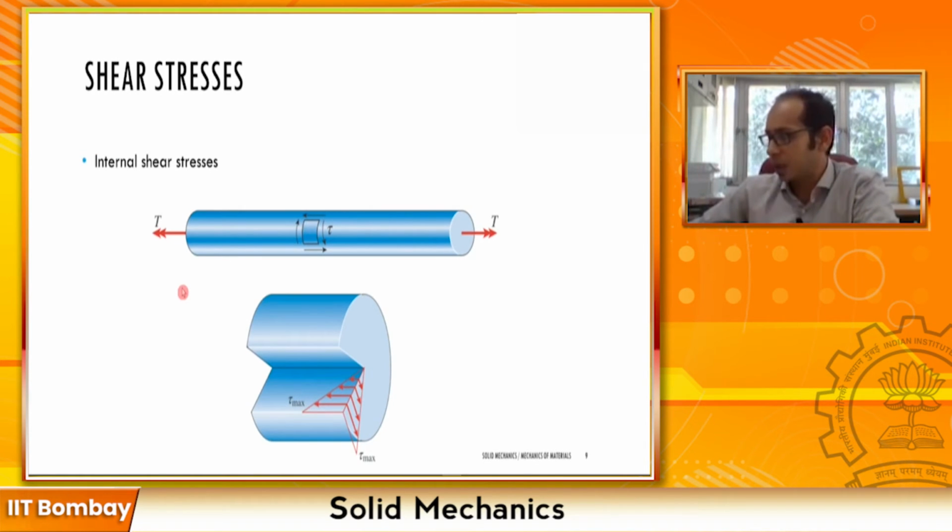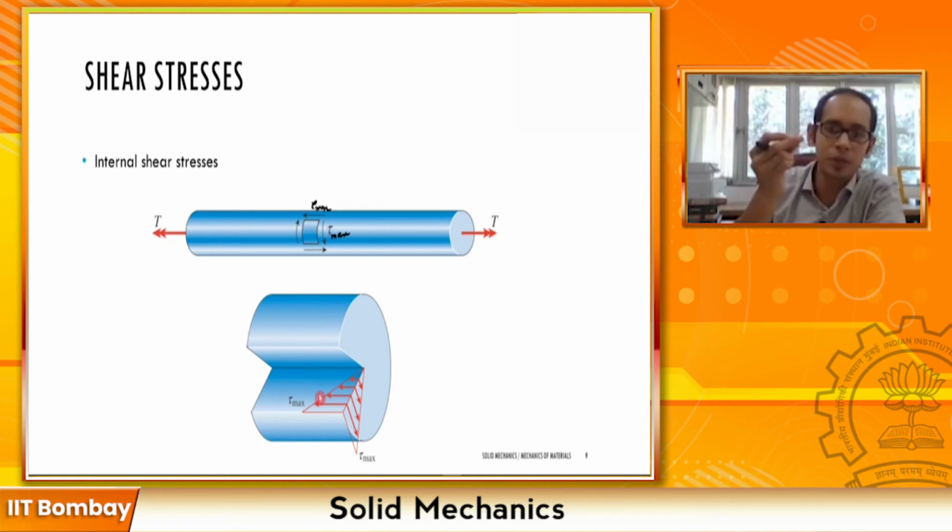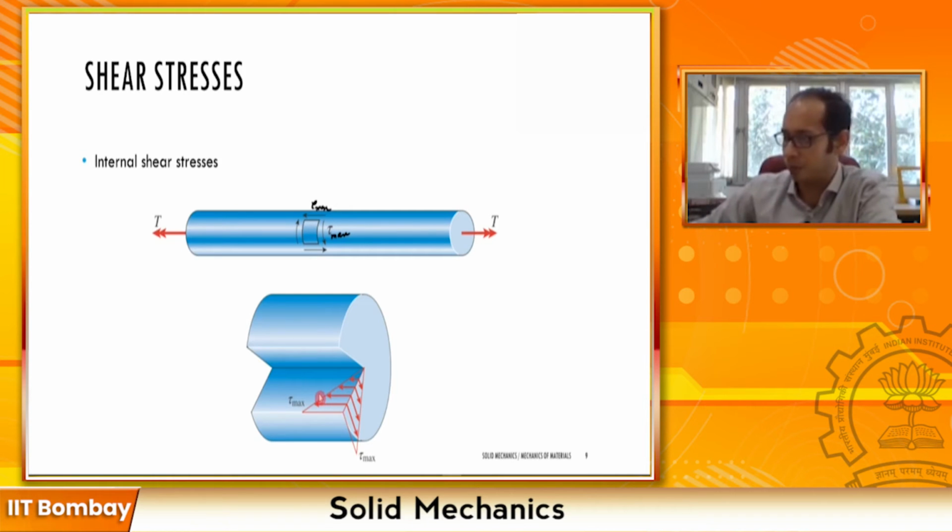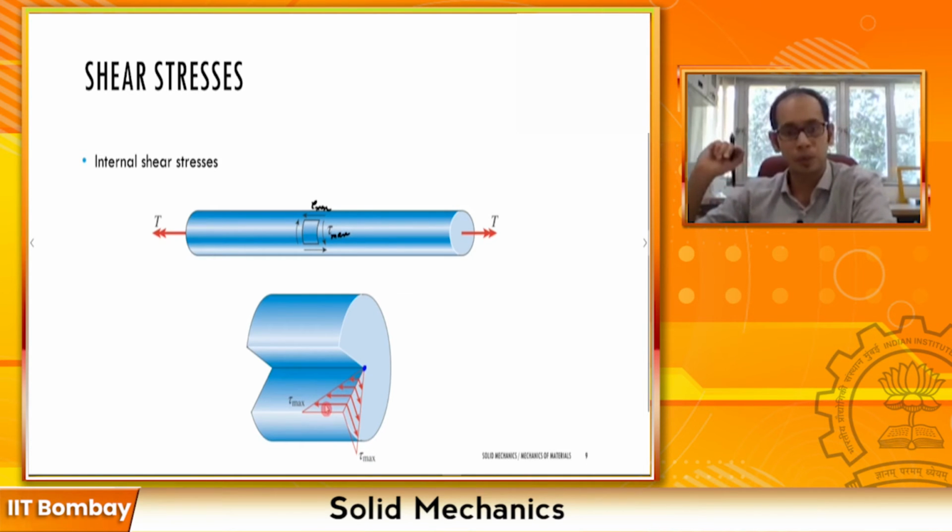It looks something like this. At the exterior, this is that exterior element, this is that tau max I was looking at on the outside. This is how the shear varies, tau max and tau max. And as you are going more and more inside, tau reduces linearly with rho till you reach the exact centroid, which is this particular point over here, where your tau becomes equal to 0 and you have a linear decrease. So this tau essentially varies from outside all the way to the inside point.